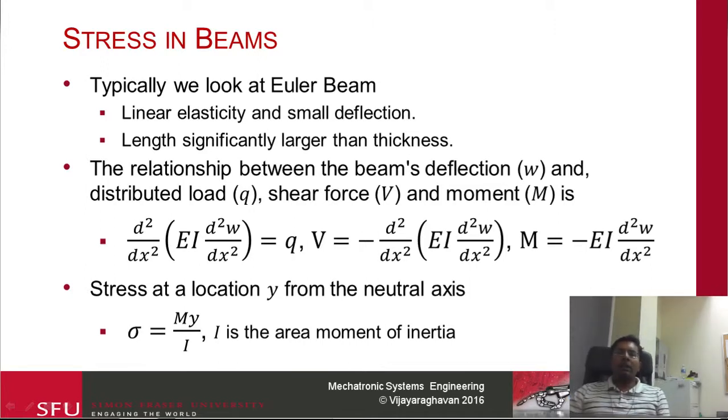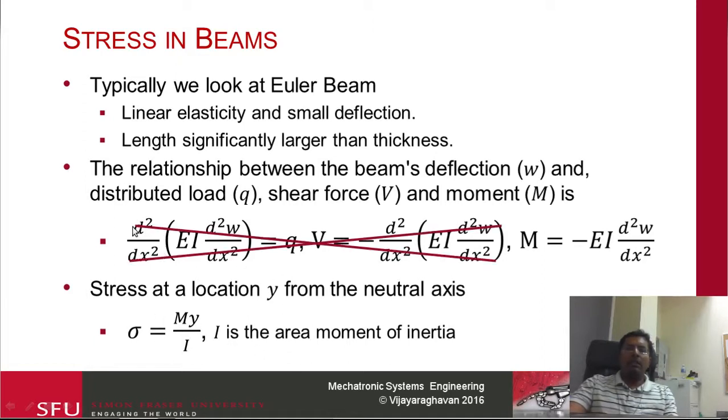The relation between the deflection W, the distributed force Q, shear force V and moment M is given by these three equations. It's basically a second order differential equation, and the stress at any location is given by My by I. Typically we are not interested in these first two equations unless you're doing a statically indeterminate calculation. So we're mainly interested only in this equation over here.